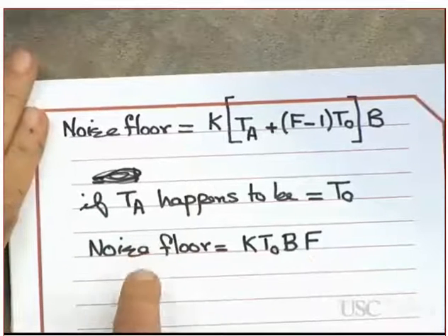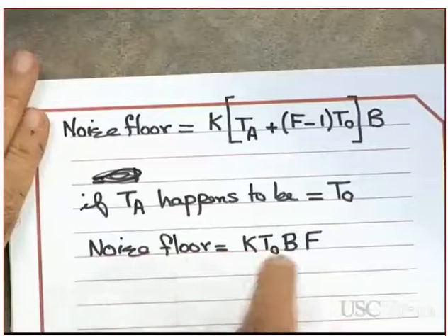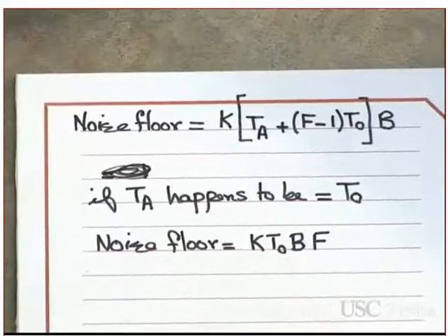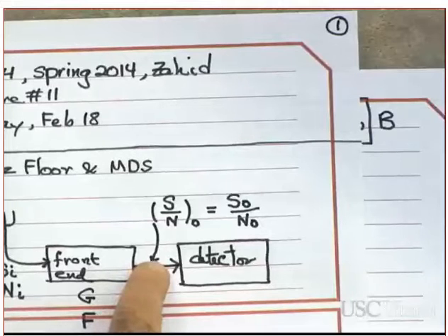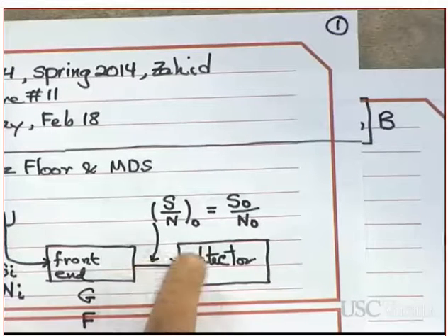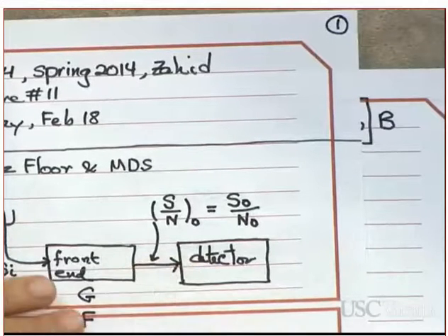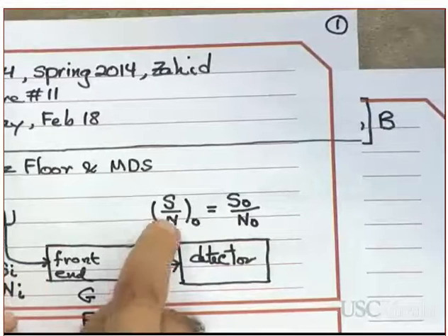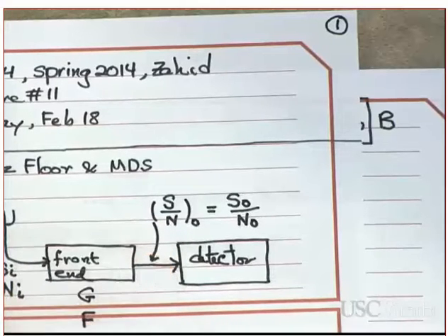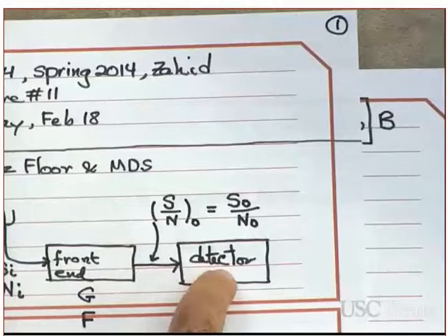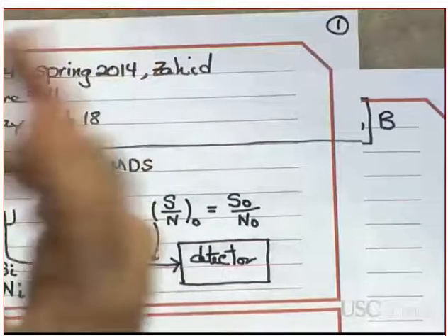Now, once you get the noise floor, you add to it 3 dB to get the minimum detectable signal, but that is only if the question does not give you any information about the signal to noise ratio at the input of the demodulator or at the input of the detector. If the question gives you the minimum signal to noise ratio, by the way, for what reason? To provide an acceptable BER.